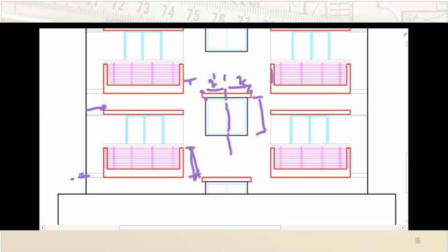And for the sunshades, these will again be not more than 6 inch, preferably 4 inch, and this extended portion obviously not more than 1 inch, preferably 0.5 inch. So that's how these are the reference lines.